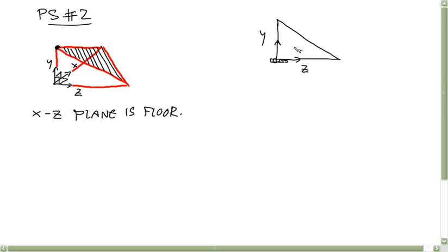For this thing to be static, if you're applying forces to it, we need something else to keep it from spinning around that hinge. And that something else is just a single frictionless contact. You can think of that as a ball bearing applied over at this corner.